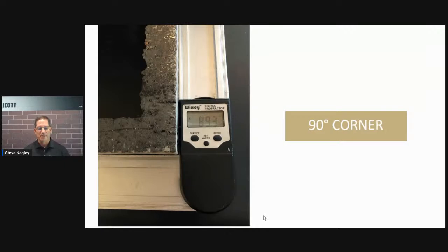But if you go back to the plant, they use this digital protractor right here to set the gauges for a PCI job or a precast job. And those gauges are made out of steel. So once they're cut out, set up, and they show 90 degrees, that's what we go by. And they have a mark to the left and a mark to the right for 1 degree. When they pull out two corners and set them in that gauge, if they don't work, they go to a pallet that says they're not PCI compliant.